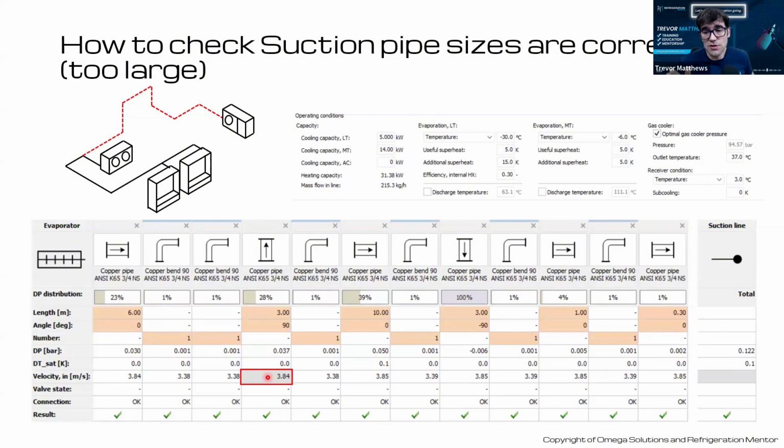If you're a technician, don't just go ahead and change it. Oh, just like Chris says, oh, well, last time it was 1.3 inches. Let's just go 1.5 inches. That'll be a bit better. Because I've had people reach out to me and say, well, the foreman said let's go with 1.5 inches because that's what he did on the last store, but didn't take into account that it was 100 feet less, you know what I mean? And then all of a sudden, now there are oil issues. And that's where you've got to get into these softwares.